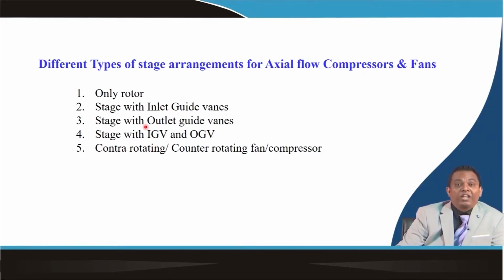We can use a stage with outlet guide vanes. We can have a combination of inlet guide vanes, rotor and outlet guide vanes, and we can also have a counter rotating configuration in which my rotors rotate in opposite directions. So let's try to understand the applications of such arrangements.